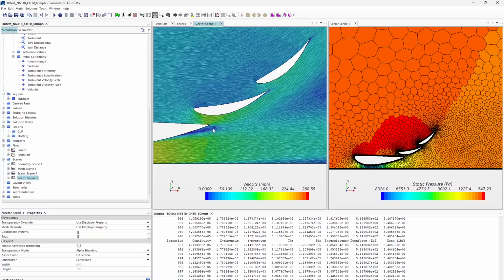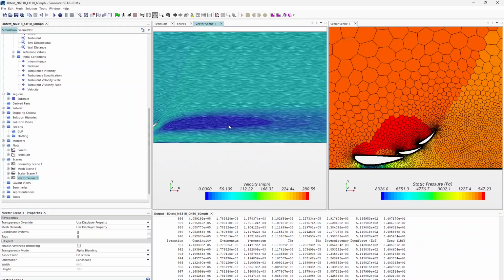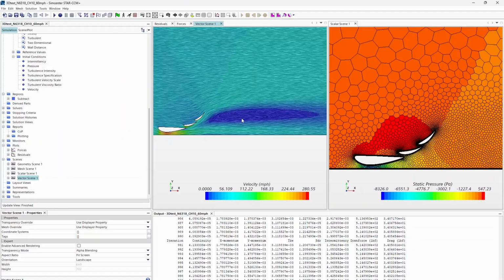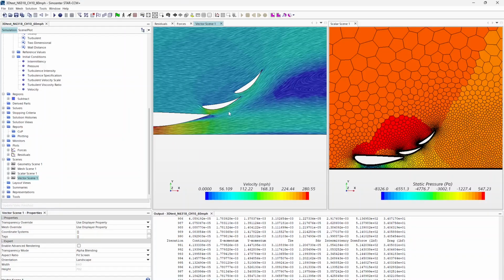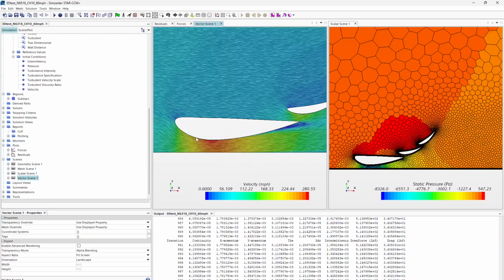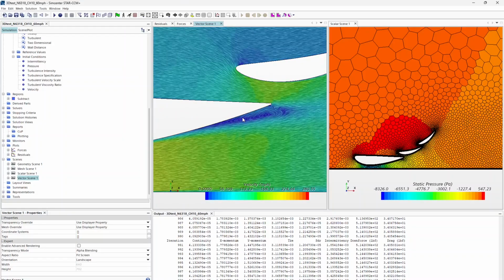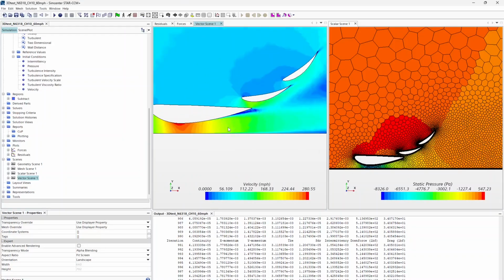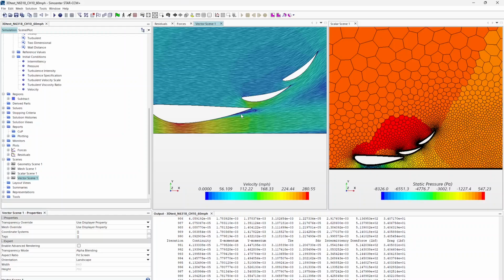we can see here what's really messing up our drag. This is not terrible at the start, but what could be really messing up our drag is this big old turbulence in the wake. And the source of this, if we follow upstream, is this separation. Now there can be separation coming off of the leading edge, but this separation is coming off of the trailing edge, which means that most likely, if we're too close to the ground and so we're choking out the air, that could be an issue, or we're really close to the ground, which is causing an adverse pressure gradient. That is a really fancy way of saying the pressure goes up.